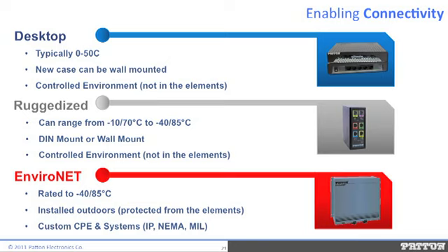Some of the products within this line support multi-drop topologies. This ruggedized or light industrial series is housed in a sturdy aluminum IP40 rated enclosure and supports operating temperatures of -40 to 85 Celsius. We can also offer additional protection against condensed humidity through the use of conformal coating.